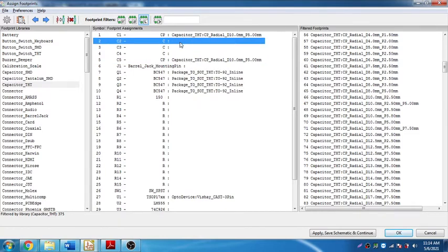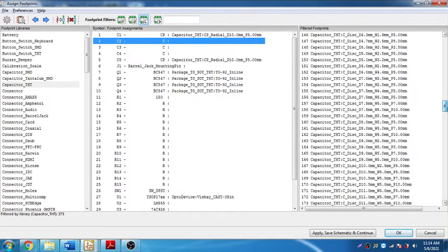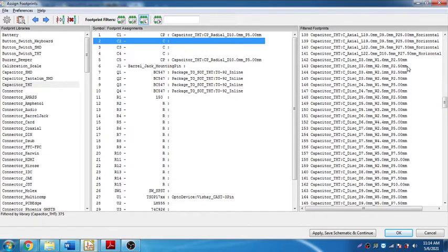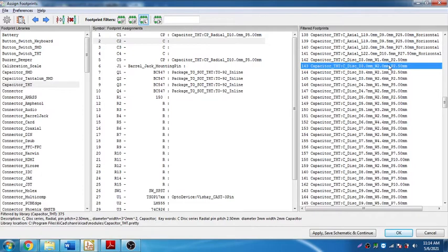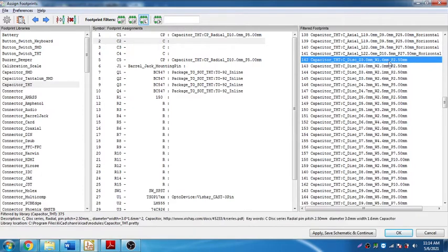And you have C2, C3, C4, they are all ceramic capacitors, and you can see that is disk type. So disk type is here. So what you do is you select it around here, disk. This is preferred for us, disk. Look at the footprint once. Yeah, this is enough for us. So disk 3 mm and pitch width 2.54 is enough for us. Or even this also, okay, doesn't matter. Okay, so I think we will go with the first one. You simply assign the footprint for that, double click each.